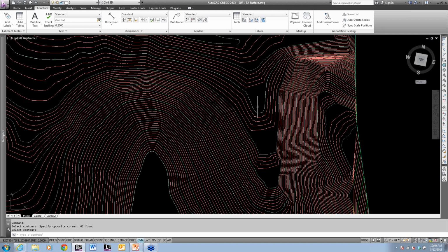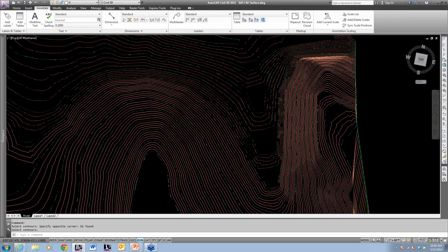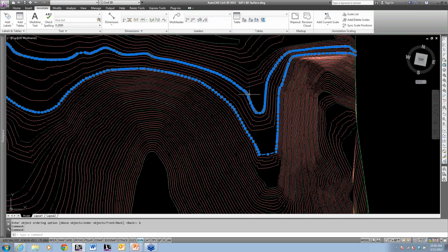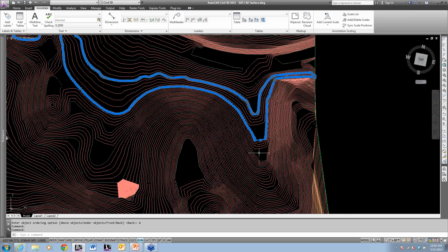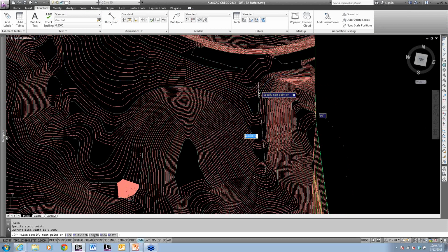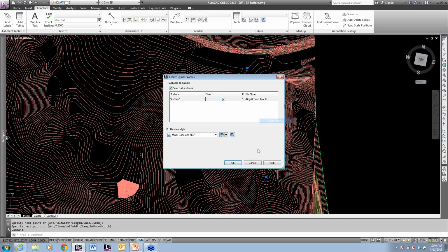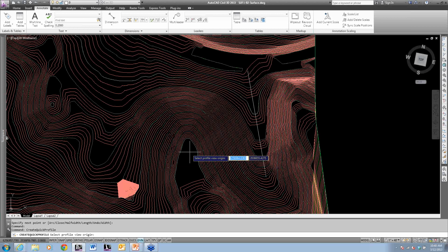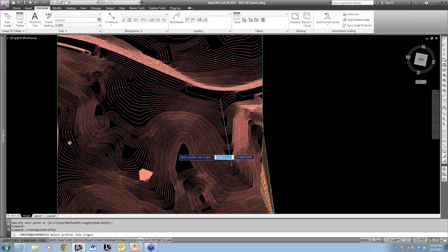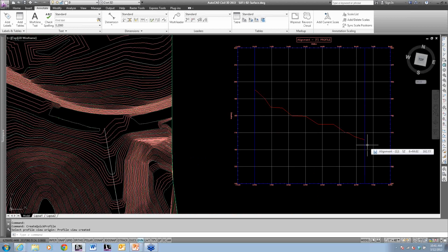All right, so here's my contour, and it's triangulating between these two 5 foot contours. As you can see, this area through here is still very flat. I draw a polyline through here and do a quick profile. So this is a draw through here. What you'll notice, I get that stair-step thing going on, and that's what I want to try to avoid.